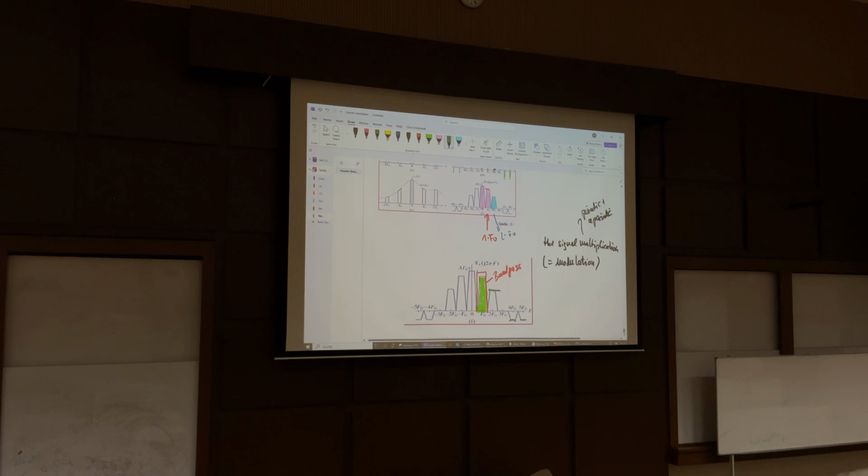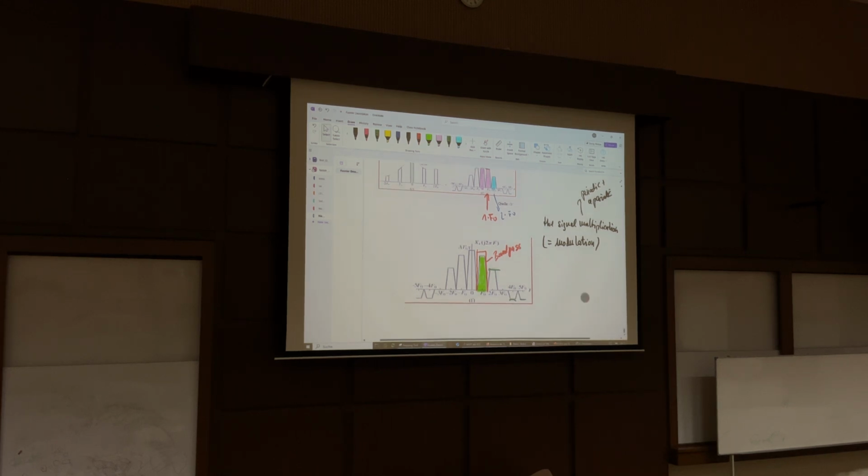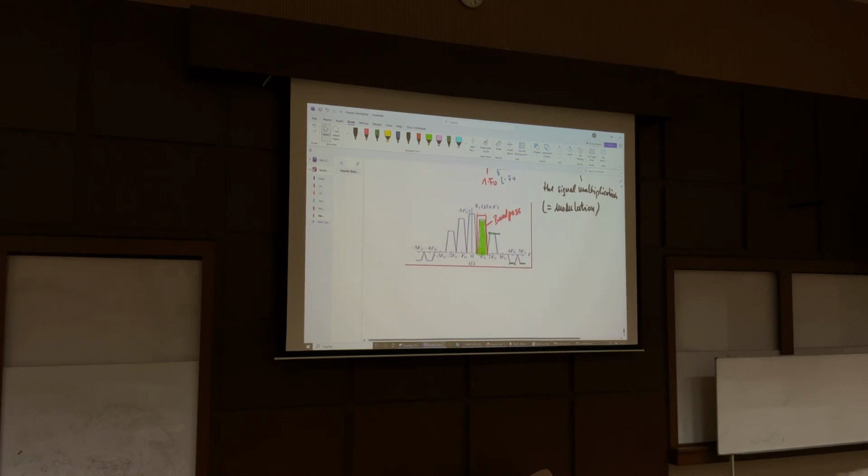And you see, the higher components have less amplitude. There are some indicated here. They are diluting to 0 the higher the frequencies are. So these multiples of the modulation frequencies, the multiple spectra, are not so important anymore because their amplitude is reduced. And that is the reason why we have this modulation.